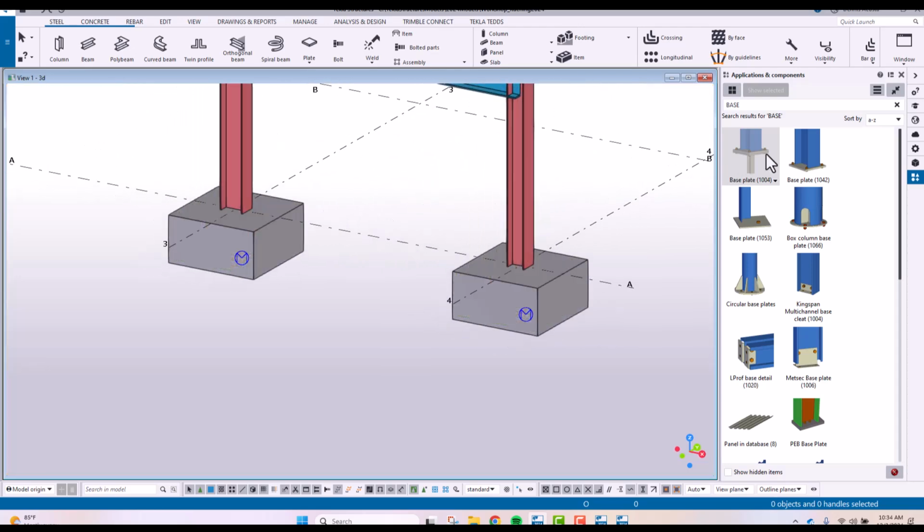Here, select the base plate. Select. So once you select the base plate, it will tell you pick the part. Correct? Pick the part. So multiple parts. Actually, it shows there multiple parts with area pick. So meaning I can select this area. Look, pick from here one. You can see the green color, meaning I cross that one to the two columns, and then pick the position. So you can pick only one position, either here or here. And there you go.